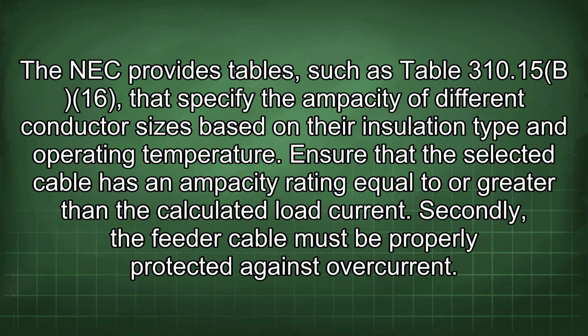The NEC provides tables, such as Table 310.15(B)(16), that specify the ampacity of different conductor sizes based on their insulation type and operating temperature. Ensure that the selected cable has an ampacity rating equal to or greater than the calculated load current.